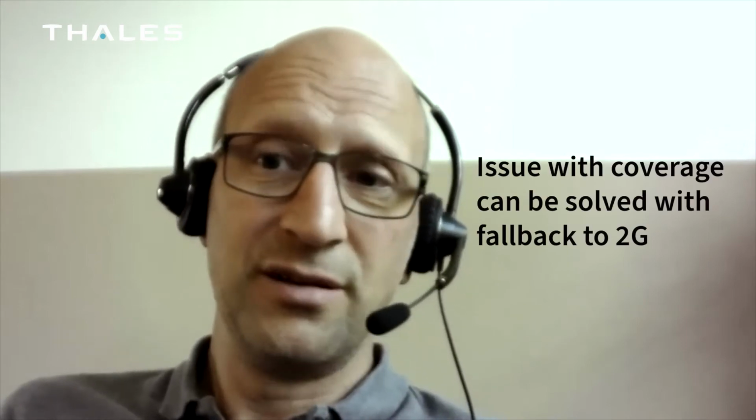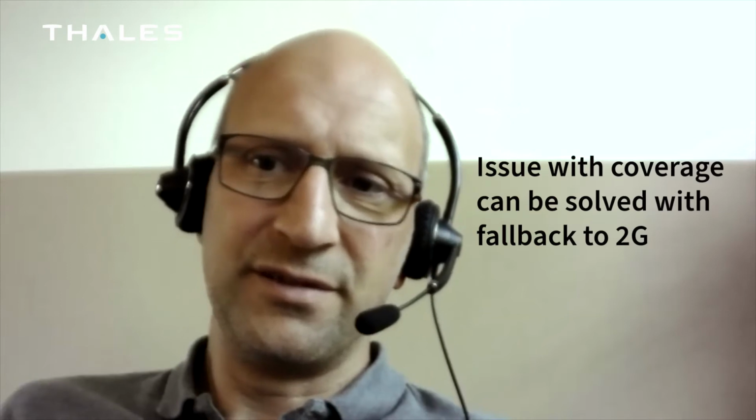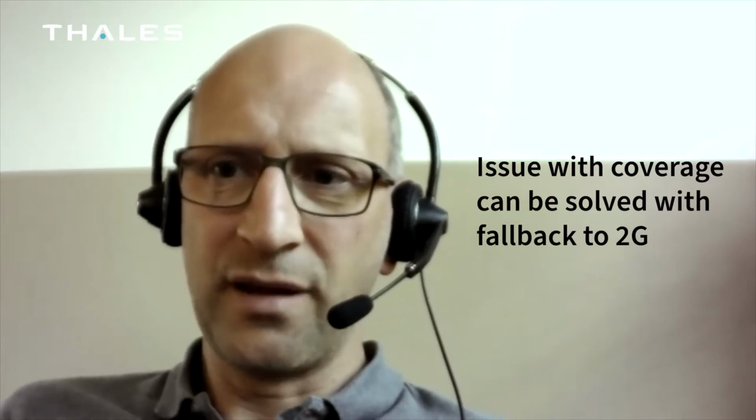But as in our EXS82 module, there would be the possibility, for example, to do a fallback to 2G, where we have the best coverage, I think, worldwide. But to get through this, a state machine in the device should handle this situation, should check the network status, or if the server side could be reached, and if not, do a fallback to 3G, and finally return to the power-saving technologies like NB-IoT or CAT-M.